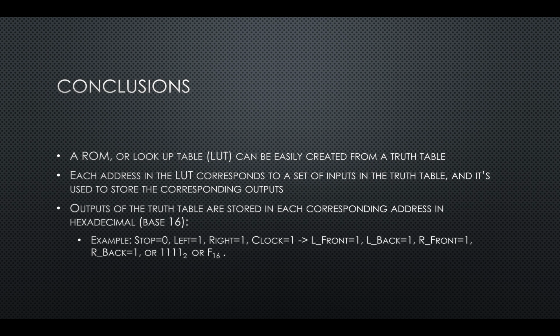hexadecimal form. For example, in one of the lines in the truth table provided, in the combination stop equals 0, left equals 1, right equals 1, clock equals 1, the result is a binary combination corresponding to 111 in binary, which then corresponds to F in hexadecimal, which is then converted back into binary as the output of the ROM and corresponds exactly to the same digital circuit that I have put together.